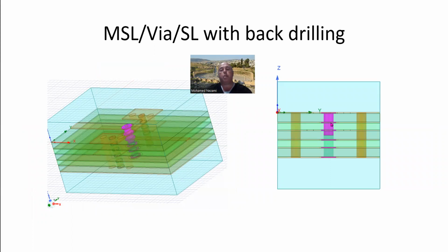After that, we said, okay, let's use back drilling. So we came in and drilled part of the inner part of the copper of that via, and we left out some of the rings because it doesn't really affect anything. In fact, you probably can choose a drill bit that drills the whole via, including the rings, but in my case, I excluded the rings a little bit and left off a fraction of a length here, just for safety, so that I don't damage the line itself, okay?